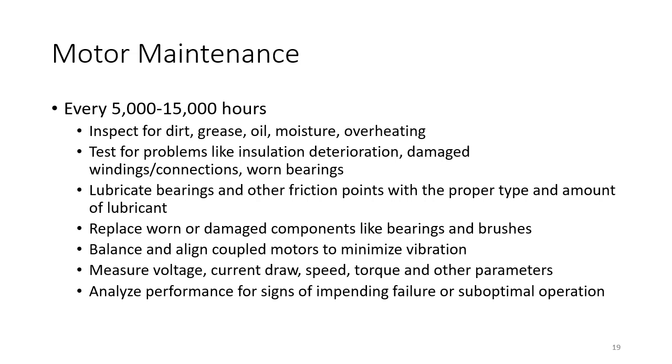The recommendation is to lubricate the bearings and other friction points. You have to use the proper type and amount of lubricant, and your motor vendor will give you guidance on that. If there are any worn or damaged components, they should be replaced. Bearings have a limited life and can often be replaced quite easily. Brushes might also need replacement depending on the type of motor.